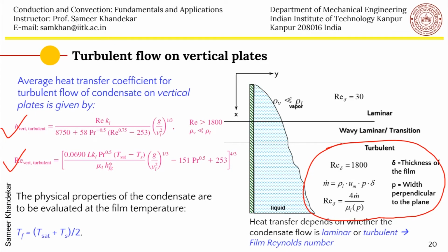And usually, as I said, the liquid films have low thermal conductivity, and therefore this conduction through the film becomes the most crucial limiting factor. So as the film thickness increases, you have seen in the expression that the heat transfer actually reduces.